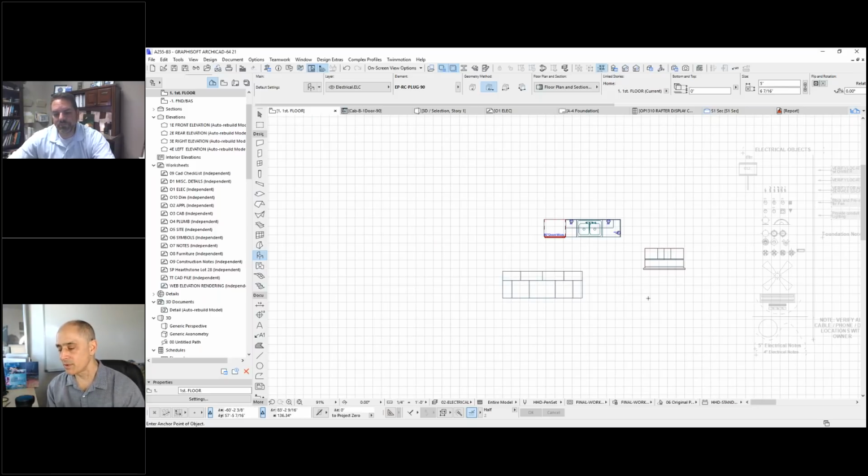All right, let me explain it again, since I think some people will not know what the heck is going on. In this particular case, Chip has made a copy of the Graphisoft object. You can open up an object definition, which is different than the object settings. Object settings is what we use all the time, when you want to change the dimension, the material or surface.